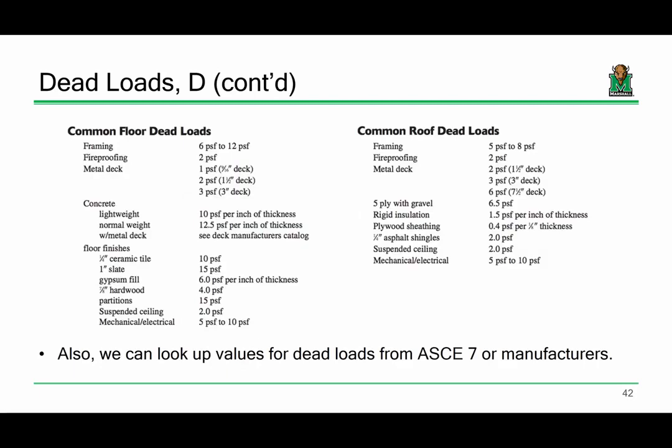Most loads are usually expressed in terms of pounds per square foot. So for instance, if we're designing this building, how much does the ceiling weigh? How much does the MEP allowance weigh, the mechanical, electrical, or plumbing allowance? How much does the carpet weigh? How much does the slab weigh? All these different components of load are usually expressed in a pounds per square foot manner.